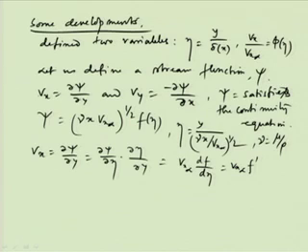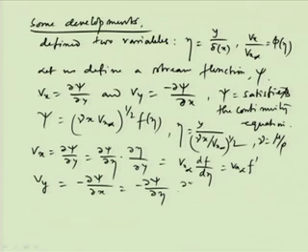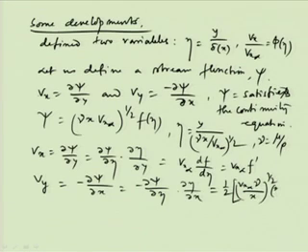And then Vy equals phi y, which is equal to minus del psi by del x, and that is equal to minus del psi by del eta into del eta by del x. So, one can do this and find this is equal to half of Vx infinity nu by x to the power half, and then eta into df by d eta minus f, like this.